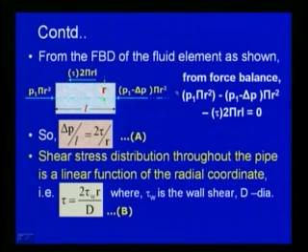So, the pressure force and the shear force you can see. From the free body diagram of the fluid element, from the force balance, since we consider the flow as steady state and laminar condition, we can write the force on this fluid element from the free body diagram.